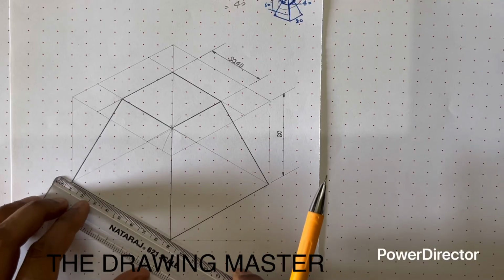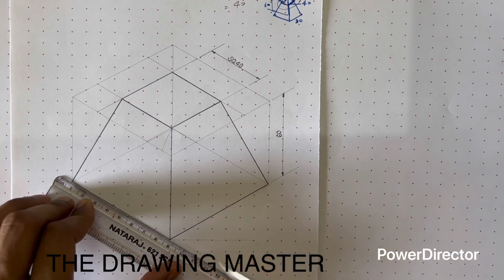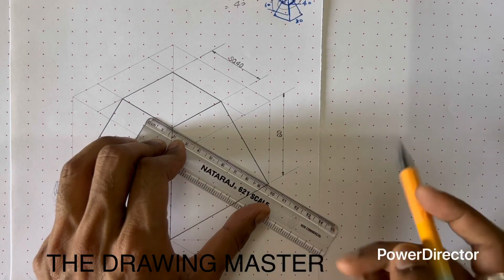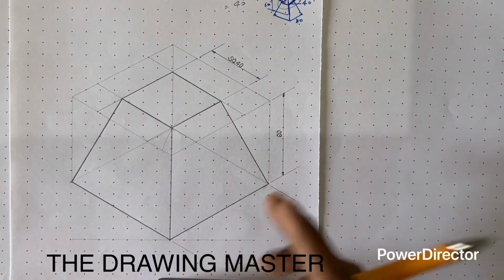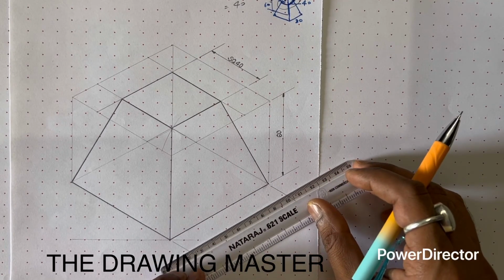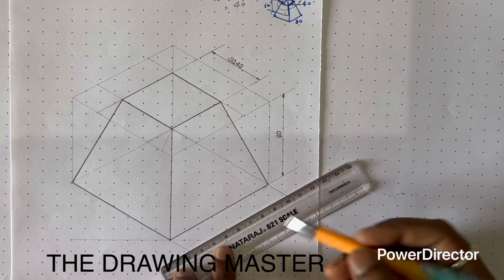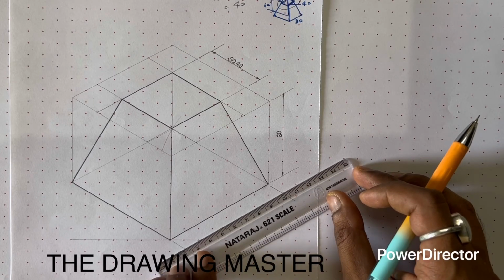Now from here we'll take the extension line, align your scale with the base edge, take the extension line, align your scale with this line, again you will get 30-degree angle. Now you can draw the dimension line. The dimension line should be parallel to the object line. You can see if the scale is parallel, you can draw the line.